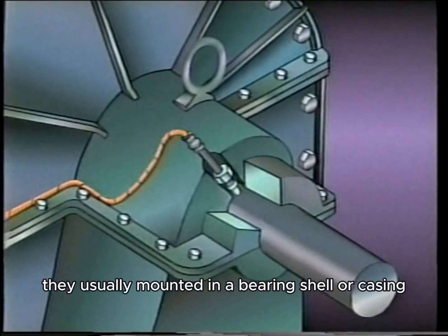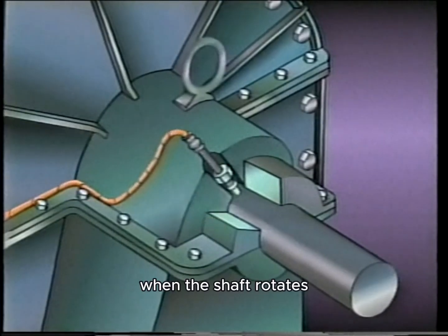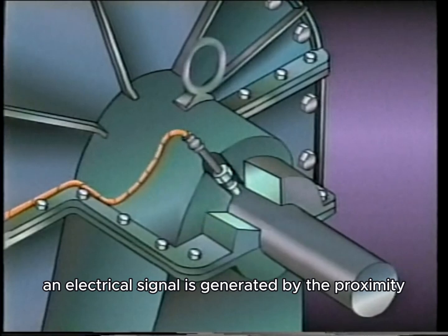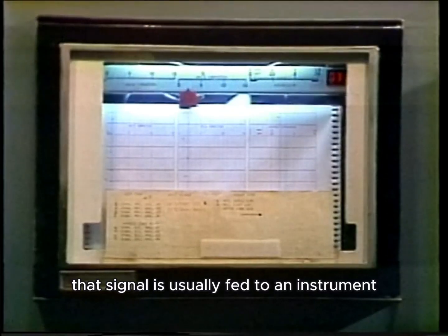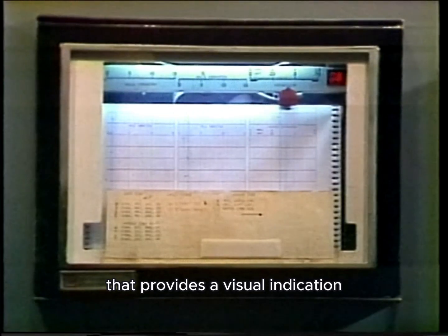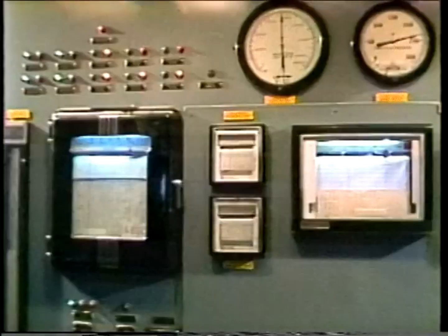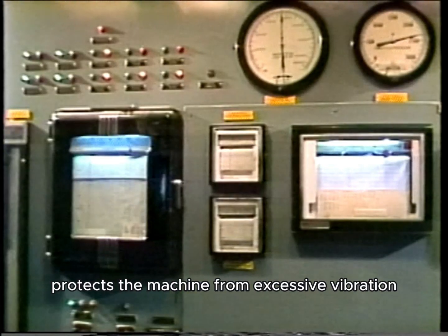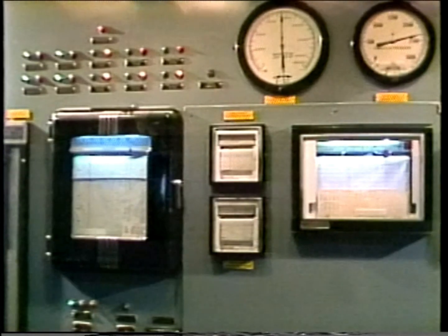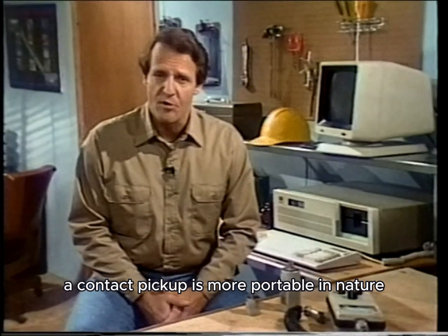They're usually mounted in a bearing shell or casing so that the probe is nearly touching the shaft. When the shaft rotates, an electrical signal is generated by the proximity probe. That signal is usually fed to an instrument that provides a visual indication of the shaft's movement for operating and maintenance personnel. The pickup may also provide input to an automatic system that protects the machine from excessive vibration. The other type of detector, a contact pickup, is more portable in nature.